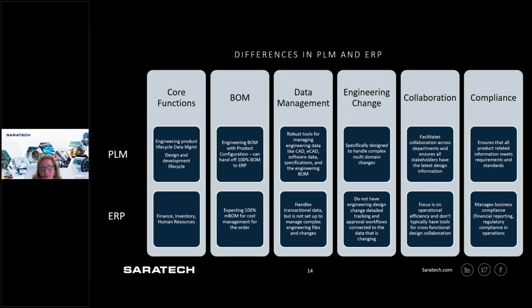When it comes to BOM management, PLM functionality delivers the CAD BOM straight from the assembly. So you save from CATIA or NX or whatever CAD you're using, Solid Edge, SolidWorks, into the PLM system, and you're going to get that CAD BOM right out of the gate. That's core functionality. And then you have the ability to create a true engineering BOM for software, mechanical, and electrical.